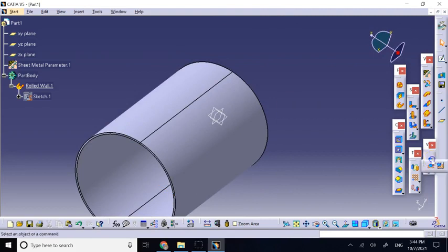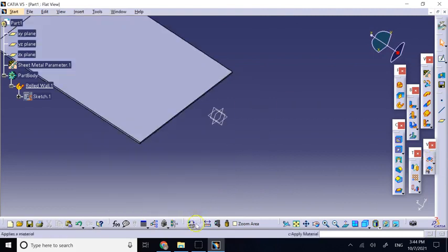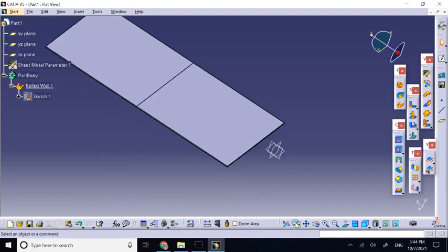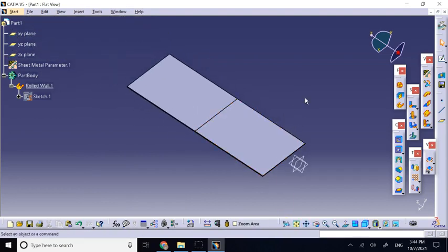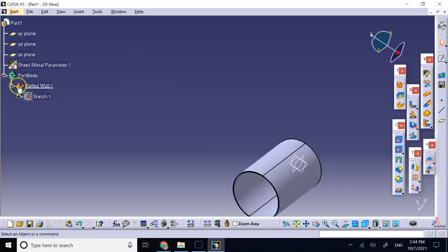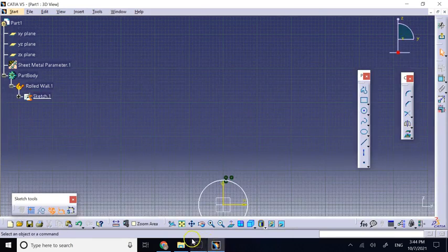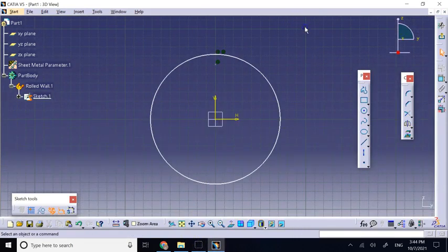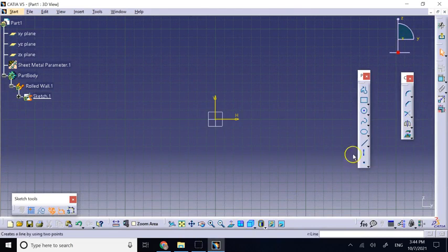So you clearly see that I can make it completely closed like this, and this is the amount of original flat sheet that I need to cut. Or if I don't want that cylinder to be completely closed because I want to use some operations on it, and then later at the end I connect the two edges together using, let's say, a welding or any other method, then I'm going to change that profile from a full circle to a 3-point arc, which is almost complete, correct?